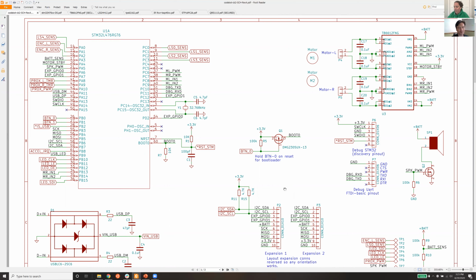I was going to bring it up, but it's going to take way too much time. It gives you a way to vary the duty cycle from 0 to 100% of on time of a pulsed waveform, and that's what allows us to vary the speed of those motors. N1 and N2 on these, each one of these H bridges really controls whether you're going forward, going reverse, or one or the other of the wheels is turning. And I'll show you that. Actually, we have that brought up here.